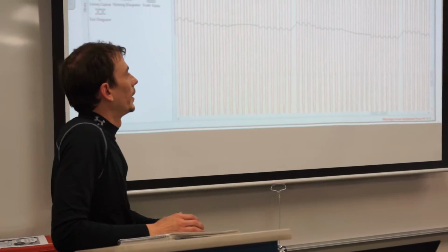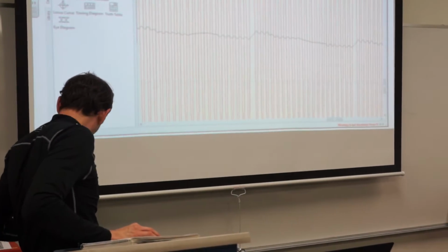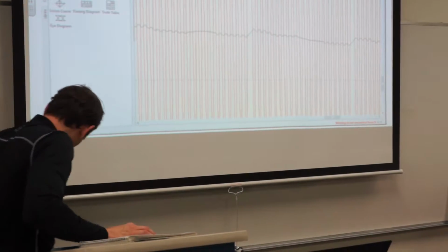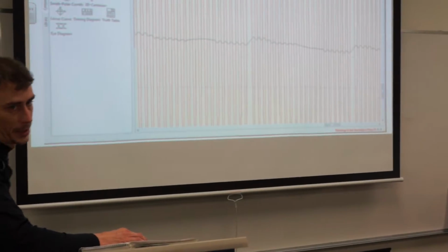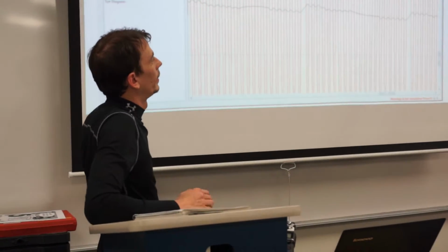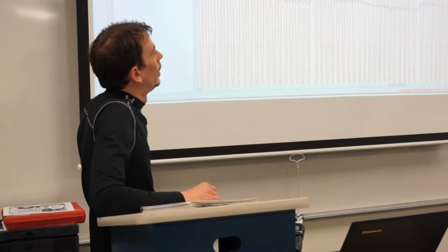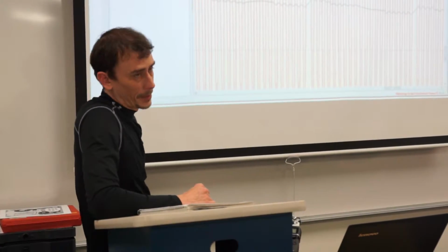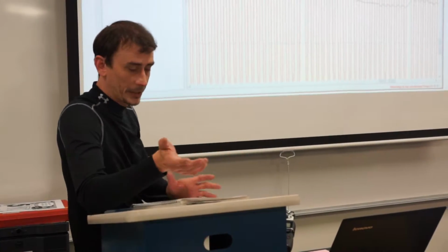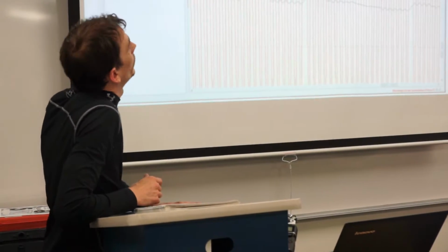The key to this design is getting this noise below the step size of our DAC. So if we're working at our 5 volt scale with an 8-bit DAC, that means our DAC has a resolution of about 19 millivolts. 19.6 millivolts, I think, is what my calculations were showing.